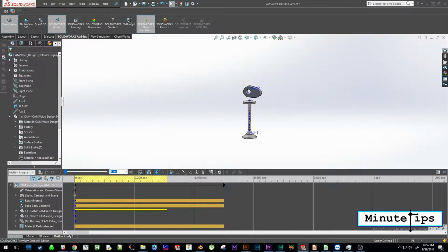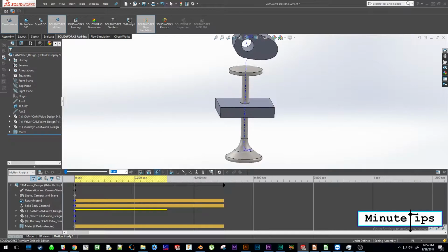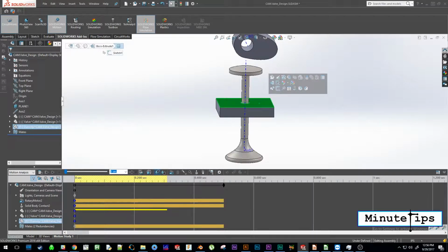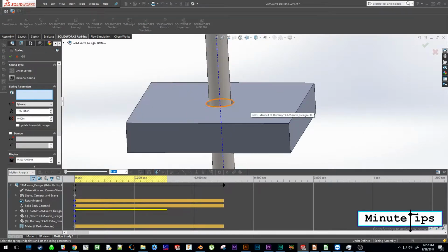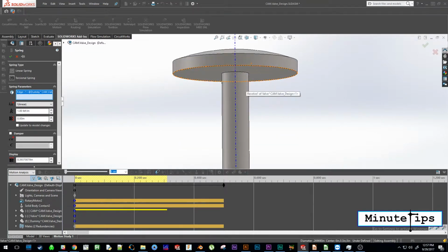Finally, you'll need to input your spring. In order to do this, you'll need a stationary surface for the spring to be seated on opposite from the seat on the poppet valve. If you haven't designed this interface yet, a simple analog like this one here ought to be satisfactory for initial design purposes. Once the seating piece is visible, select the spring feature here and click on both the concentric edges of the seat and the concentric edge of the valve stem respectively.